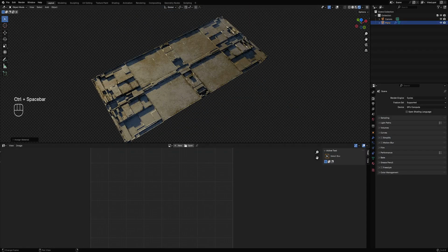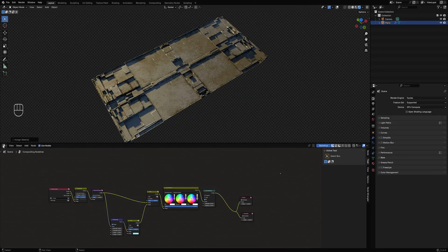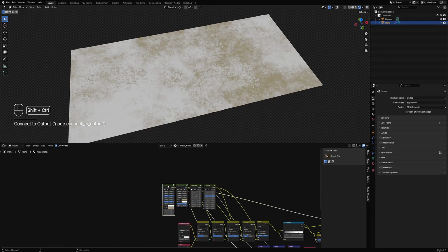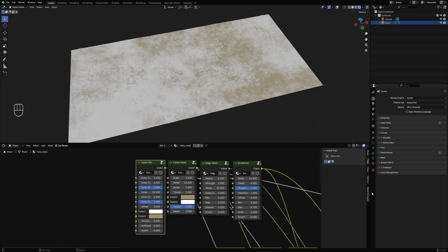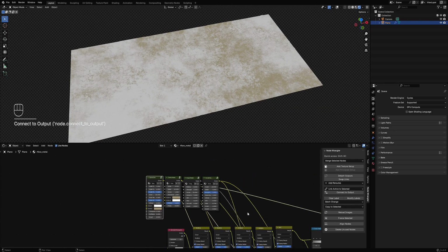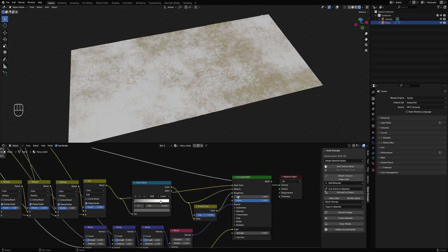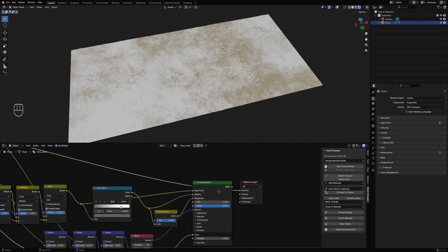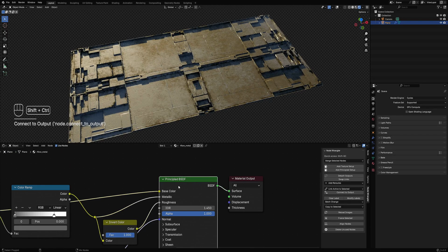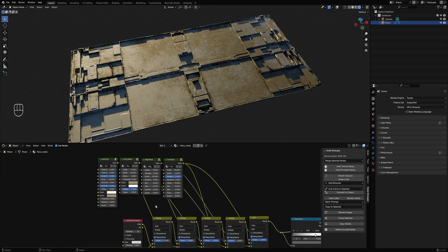edit this first. So let's go into shading and look at the result of the quick dirt. You need to have Node Wrangler activated in order to use this feature. So basically Control Shift click on a node and it will show you the preview on the viewport. Then to get back to the original output of the shader, Control Shift click on the main shader and then go back to the original result.